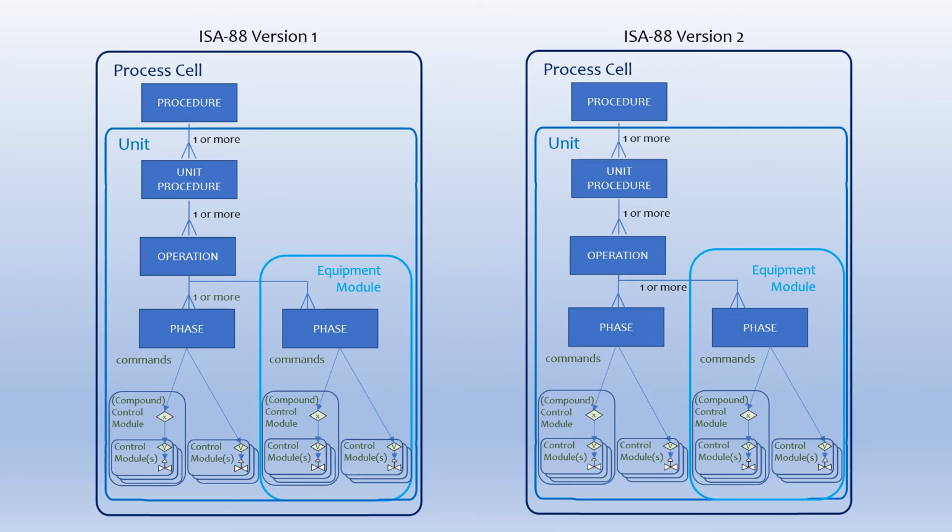The misinterpretation of the term equipment module, while probably less consequential, was trickier to include in the new unified ISA-88. Starting from the name conflict, two simple solutions come to mind. Solution 1, send out a memo to all the miscreants to stop calling compound control modules equipment modules. Let's call this the King Canute option. Solution 2, install my preferred option if there's a version 3 of ISA-88. Accept reality and rename compound control modules as equipment modules, and rename the physical entity equipment module as minor unit, which I think suits it better.